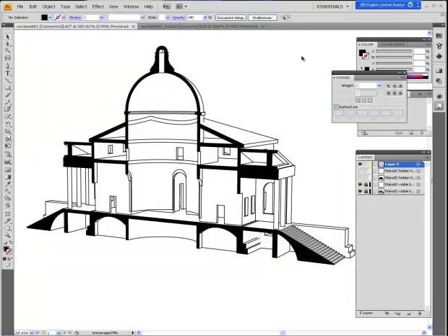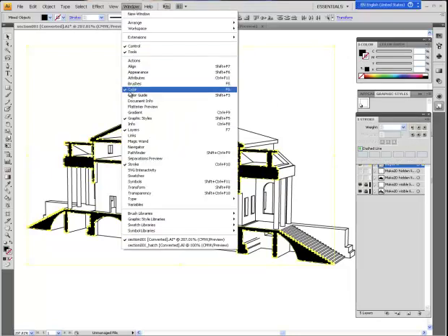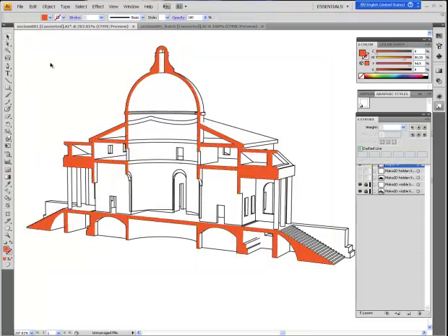And then I want to change the color. Click the one and make sure that you have a color window. How can I turn on the color window? Go to the window menu, then you are able to select color window, layer window, stroke window, and so on from here. With the color window, select the object, then you are able to define the color of the line and the color of the fill. I want to change the color of the fill to kind of orange, red. Okay, and then it's too strong. What I want to do is change the transparency. Click it, and change the opacity over here.